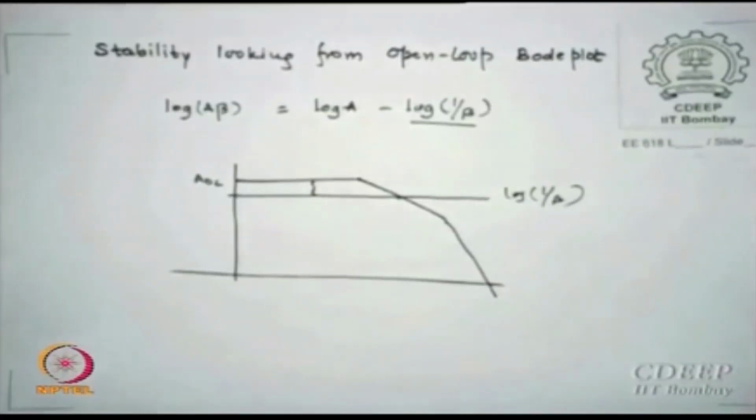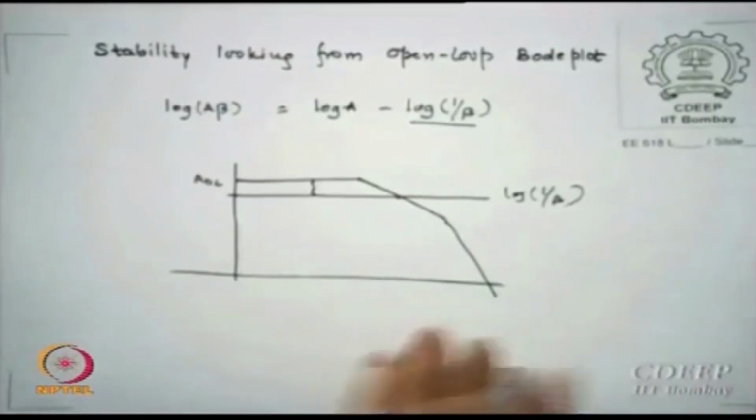So what is the thumb rule? If you have an open loop gain, see to it that your feedback does not go beyond the second pole; it should be within the first pole and second pole. If you can fix this value there, you are 100% stable. So that is how, from the Bode plot, by just looking you can say, oh, it's stable, okay.